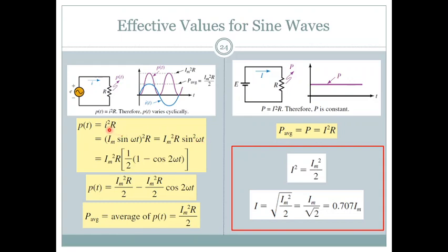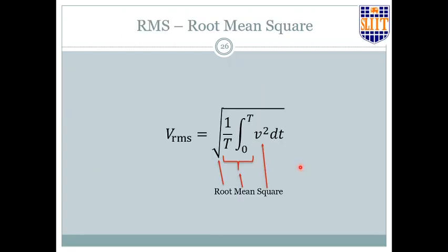Now this is a current, right? Power should be integrated over a period of time. So what is integrated is the square, averaged, and we'll have to take the square root as well, of course, because we are doing the square root in here. So the square is integrated, actually averaged over a period, and then the square root is taken. This gives you the effective value, because that is the same procedure that we followed so far, with different techniques, of course.